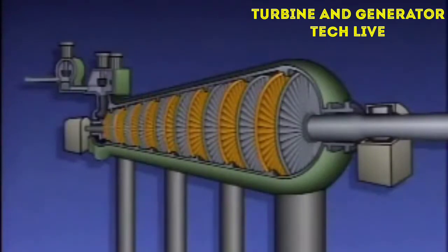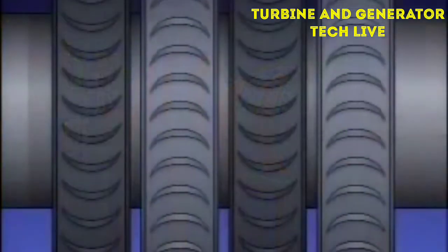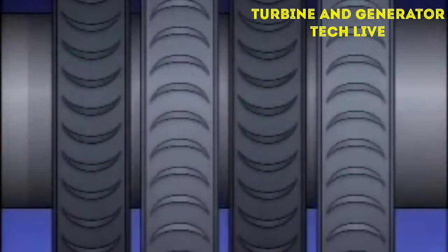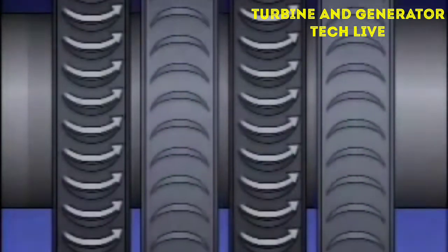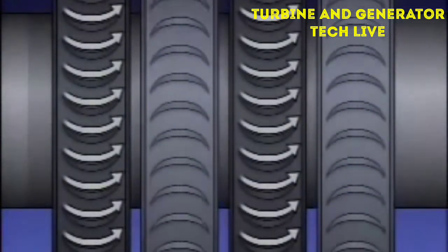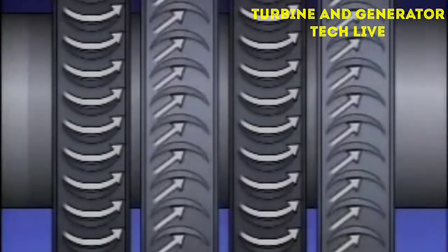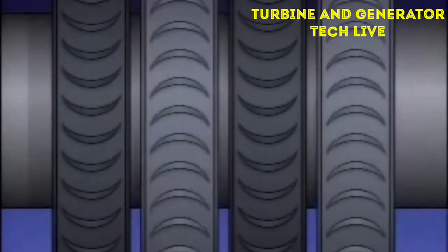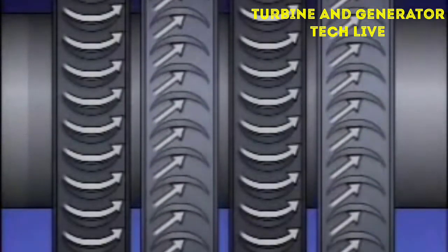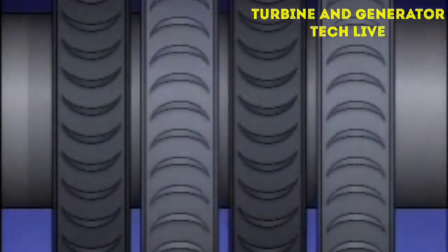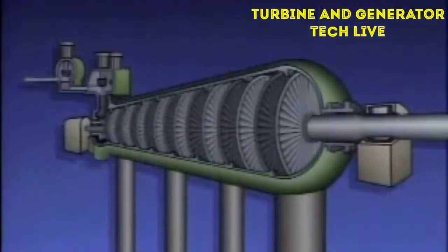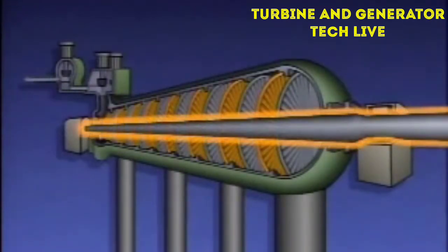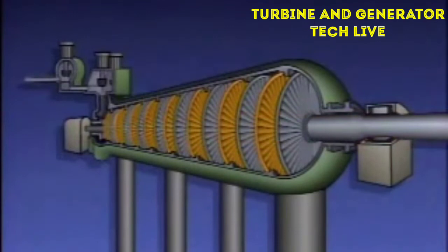The distinction between diaphragms and wheels is the way they function during turbine operation. Diaphragms are stationary and their blades are fixed in position. Their function is to direct the flow of steam leaving one set of rotating blades into the next set of rotating blades. Wheels, on the other hand, are moving parts. They are designed to turn as the steam flow passes through their rotating blades. The rotation of the wheels turns the shaft and the generator. Diaphragms are sealed where the shaft passes through them to minimize steam leaking through this opening and bypassing the diaphragms.